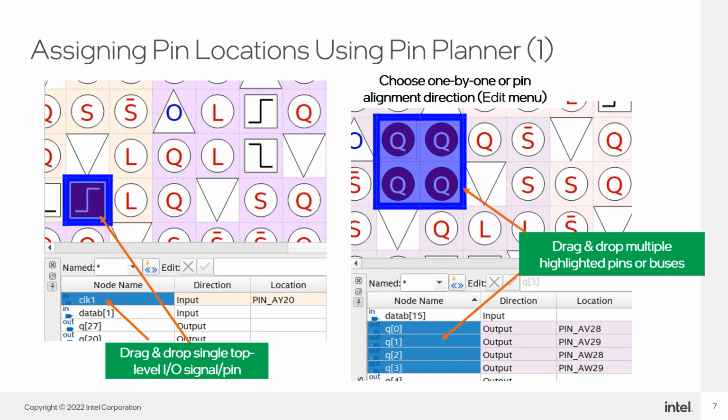There are a number of ways to create I/O location assignments in the Pin Planner. The simplest is through drag and drop. Select a signal from the Groups or All Pins lists, then drag and drop it onto a pin in the package view. As you hover the cursor with the signal over pins in the package view, tooltips appear to provide information about some of the functions of the pin to help you decide whether to place the signal at that location.